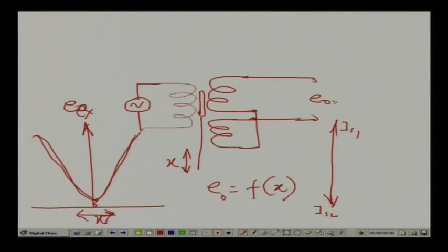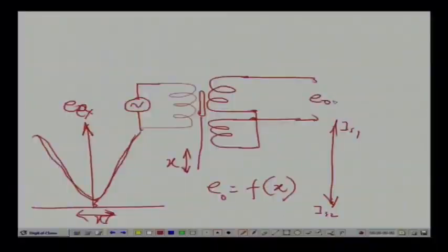Whenever you use an LVDT, you need a separate excitation voltage, because it is like a bridge. As you know, a Wheatstone bridge also needs an excitation, either DC or AC, it does not matter, but in the case of LVDT, since we are using a transformer, there is always an excitation. This can be easily avoided if I use a particular chip available, where you can also vary the frequency of excitation, and I get an output voltage which is free from all these problems.